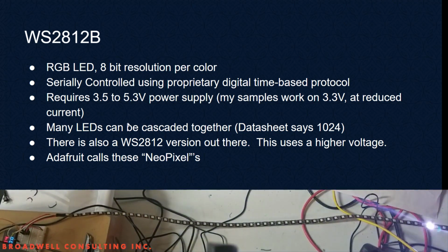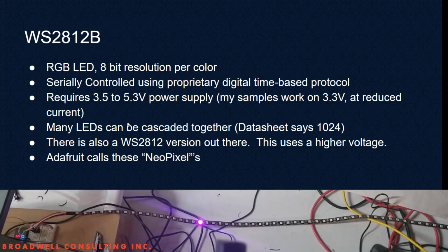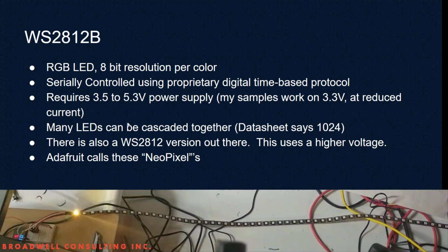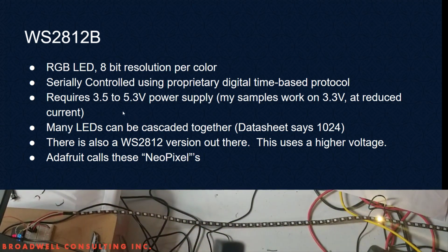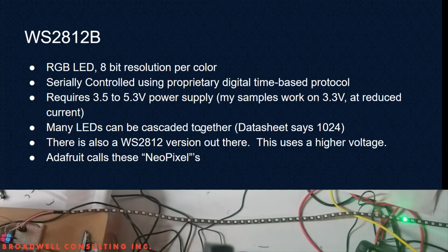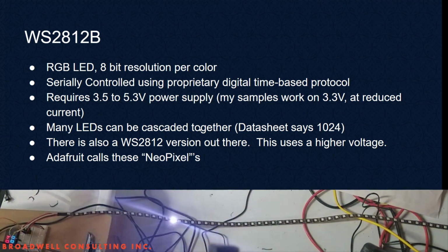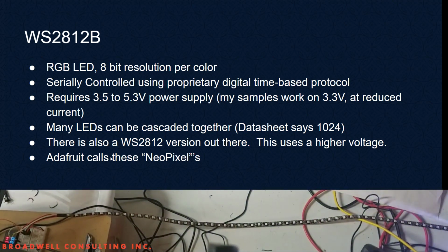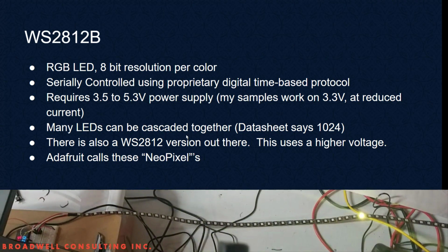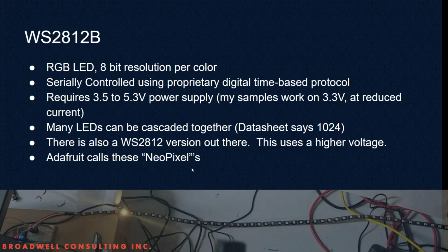This is how almost all the LEDs you see are used, in a string or 8x8 matrix, or in our case, a circular display. There's also a WS2812 version out there. This is an older version. It requires higher voltage. People say that it has worse color balance. Adafruit calls a variety of LEDs that use this control scheme NeoPixels, so occasionally you'll see that name as well.